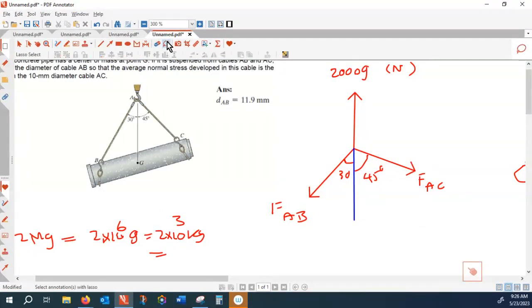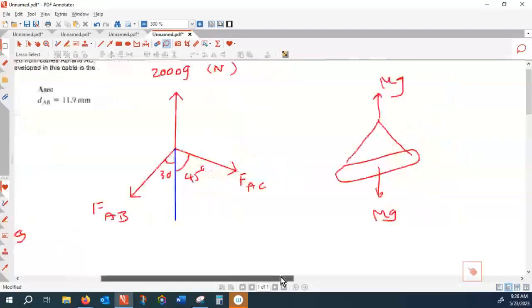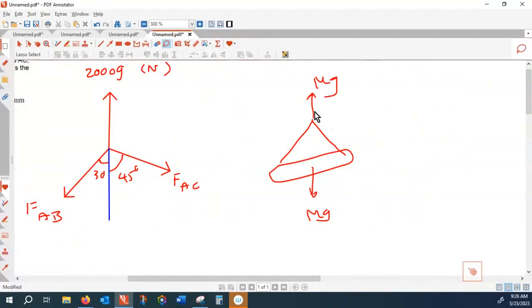Look, if you don't cut the cables, what is the free body diagram? This is an envelope, my envelope, right? So my envelope is separated from the universe only at the hook. So the hook's internal force should be exposed, and that is a free body diagram like so. I just released that from the hook. So for the hook to hold this, the only force here is mg. So the hook is taking mg.